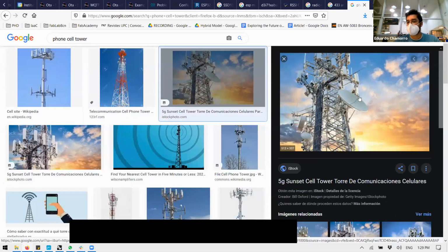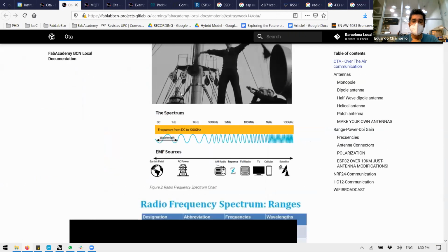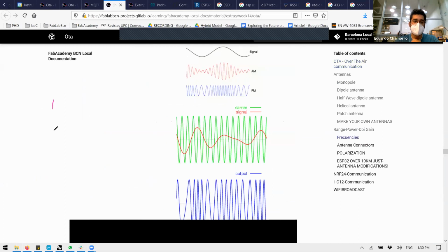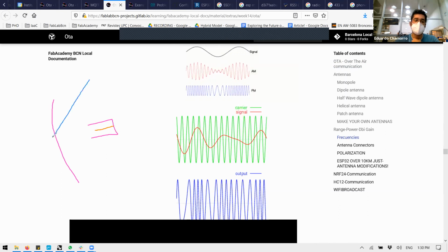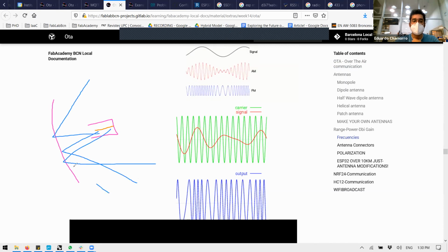Then we have the circular, plate-like antenna that is really, really directional, that we will focus on. Actually, with antennas, something that is a common misunderstanding is that this is the sensing part. No, actually the sensing part here is this. In this kind of antenna, we have a dish, and we have the active element here. What we do is concentrate the radio waves bounced from multiple directions into here. The dish bounces back the signal and it gets into the active element.